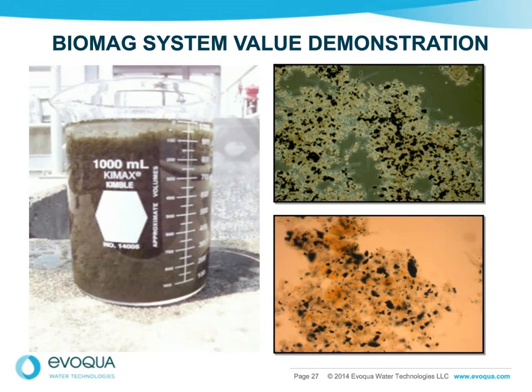It can be biologically related to filament or sludge bulking issues. It can be Nocardia outbreaks because you're trying to do enhanced nutrient removal and require long sludge ages, and you have issues where you get Nocardia and foaming issues. And then typically the clarifier is the Achilles heel, the bottleneck of the system. And BIOMAG overcomes that bottleneck.